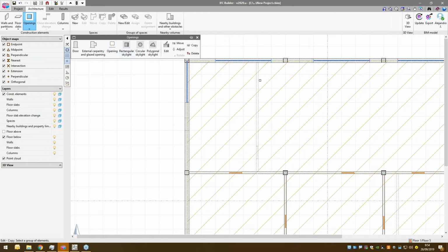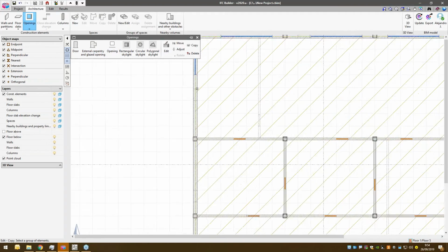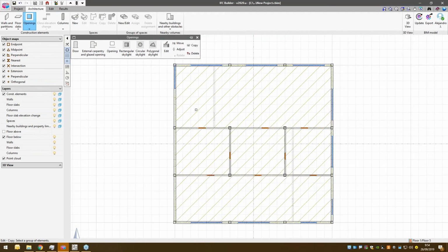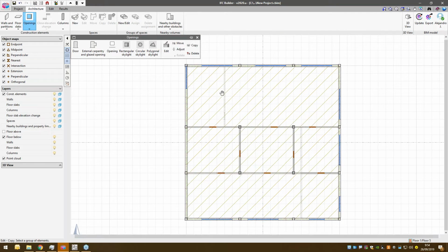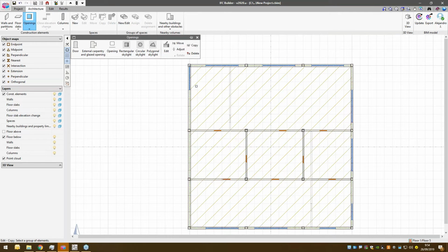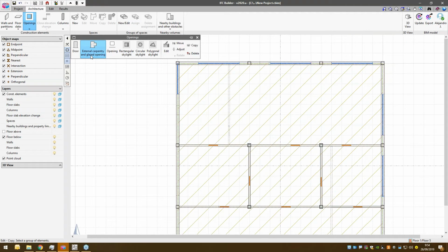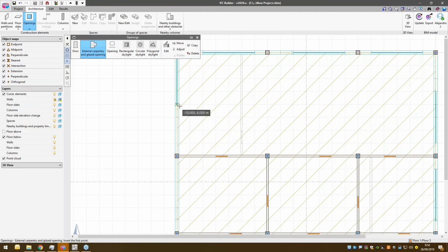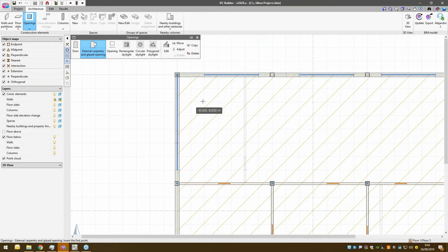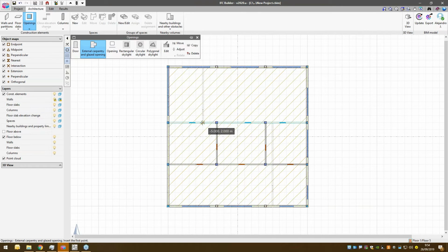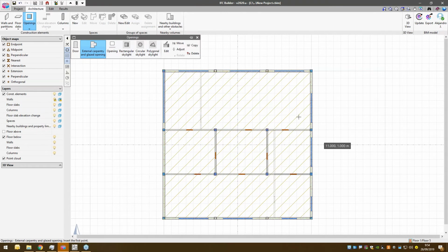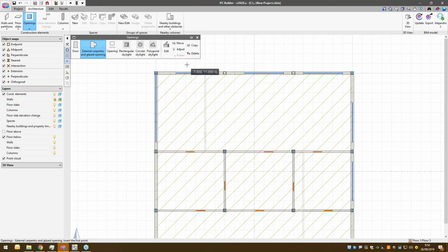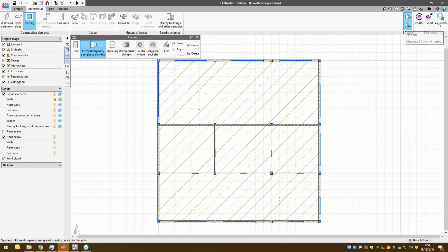it is not that easy to define a glazed plane and afterwards to conduct a thermal calculation, even though we are developing technology to be able to do that and define these kind of elements as curtain walls, the same way as another software such as Revit would do that. For now, you have to stick with this method, which we know is not the best solution, but it is what we have now in order to be able to reuse this model for later calculations.